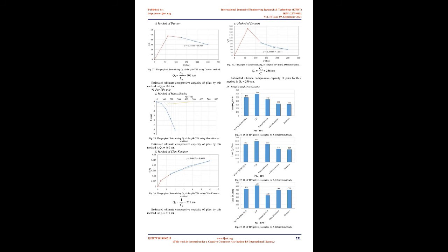Set the symbol QD to be the working load of the pile. Calculate the ratio between Q and QD and those values are compared between test piles as well as between different calculation methods. The results are presented in Figure 37 and Figure 38. Some of the comments made are as follows.